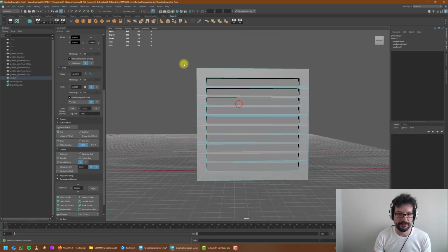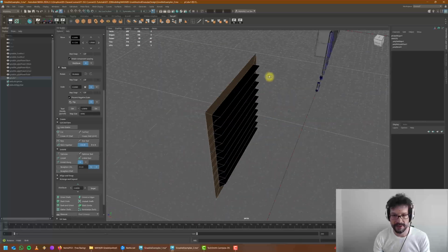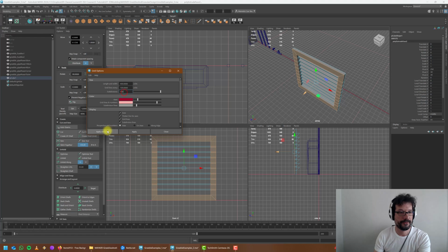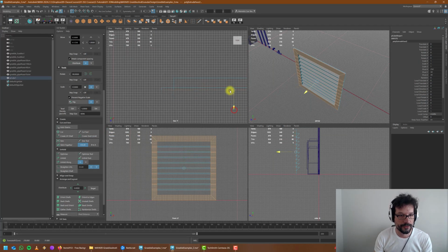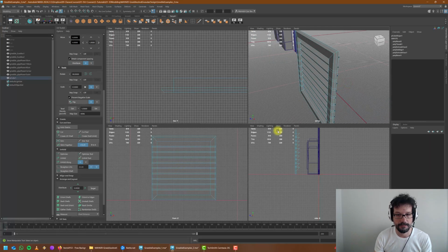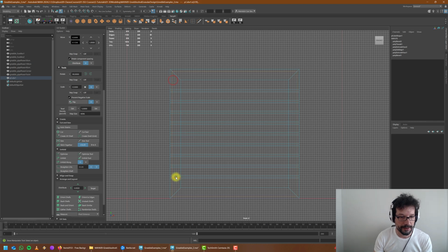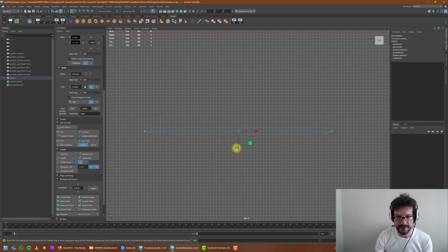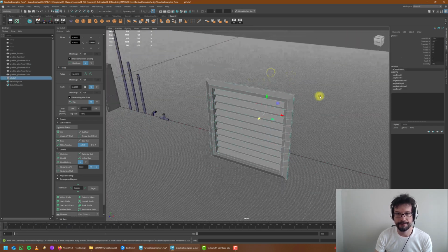Okay, now I can grab all of the front faces like so, make sure nothing is selected, and let's extrude them. Okay, and I don't know, maybe extrude them 2 centimeters. Okay, good. Grab the outside edges, bevel them like so. Okay, and I even want to push these bevels a little inwards. Not a symmetrical bevel, but larger on one side. That's the kind of bevel I want in this case. Okay, nice looking bevel. Make sure this is on the centimeter itself. And there you go.